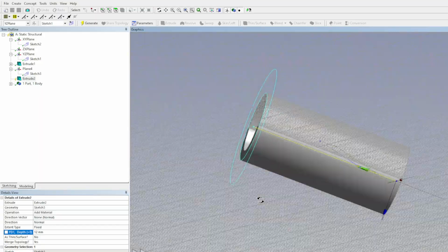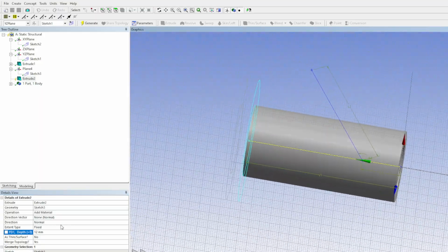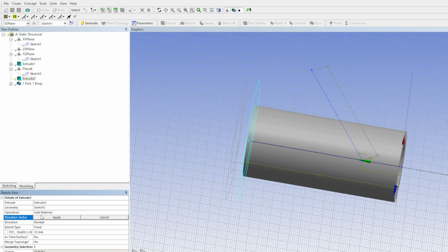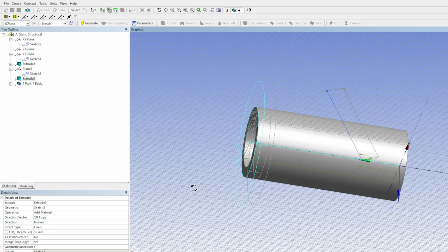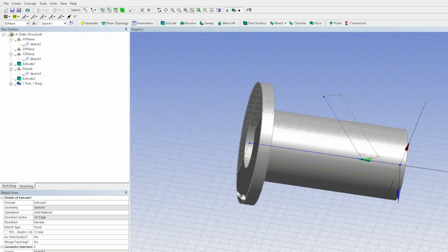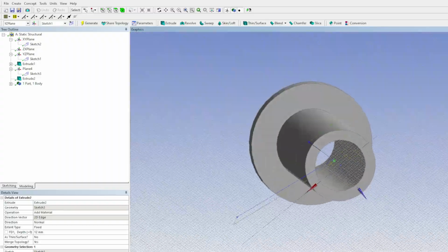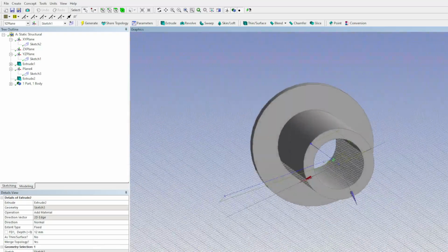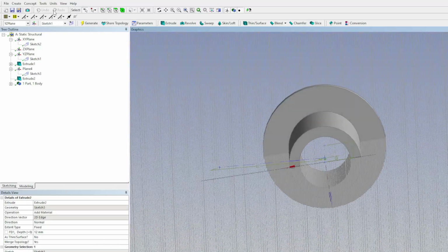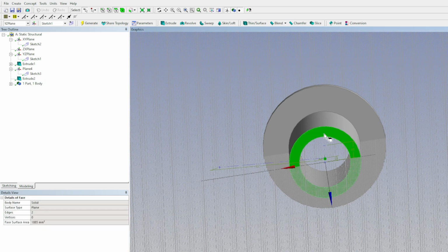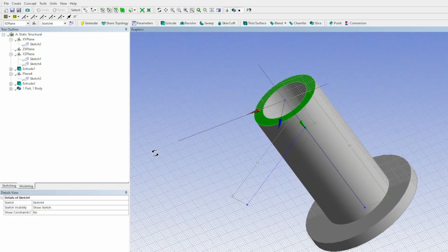And you can see it's still on the wrong side for what we want. So, looks like this wasn't applied. There we go. And now if we hit generate, boom, we have one side of the end tube done. Alright, so now I'm going to do the same thing with this other end. We can click on the face tool up here, select this face, and click New Sketch.